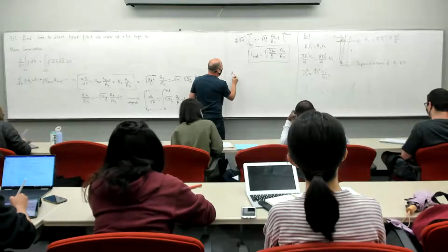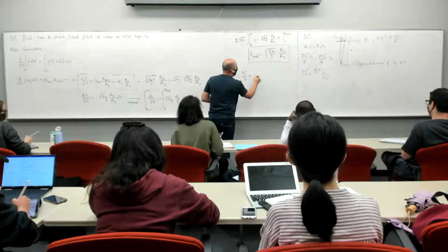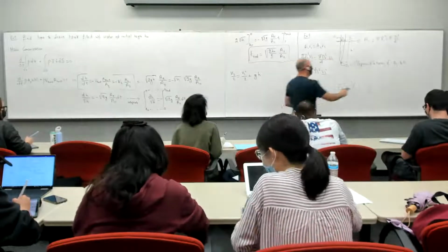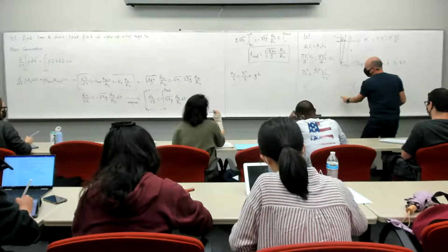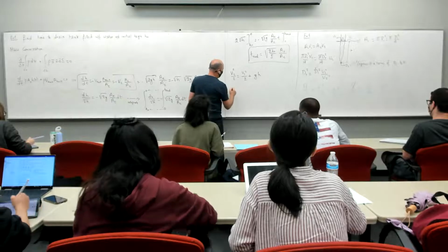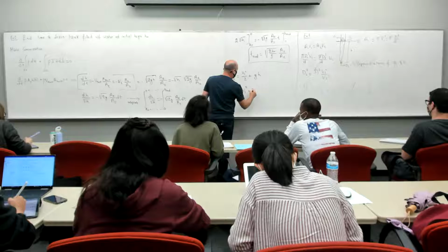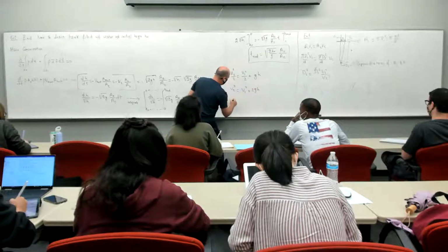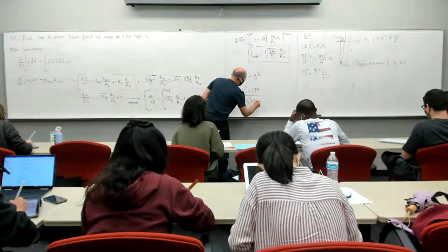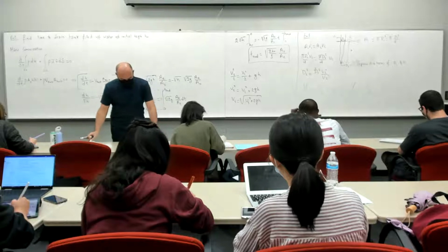So you get V2 squared over 2 equals V1 squared over 2 plus GH, correct? So GZ1 minus GZ2, and then you get V2 squared equals V1 squared plus 2GH, and V2 equals the square root of V1 squared plus 2GH, correct? Is that what you got? Okay.